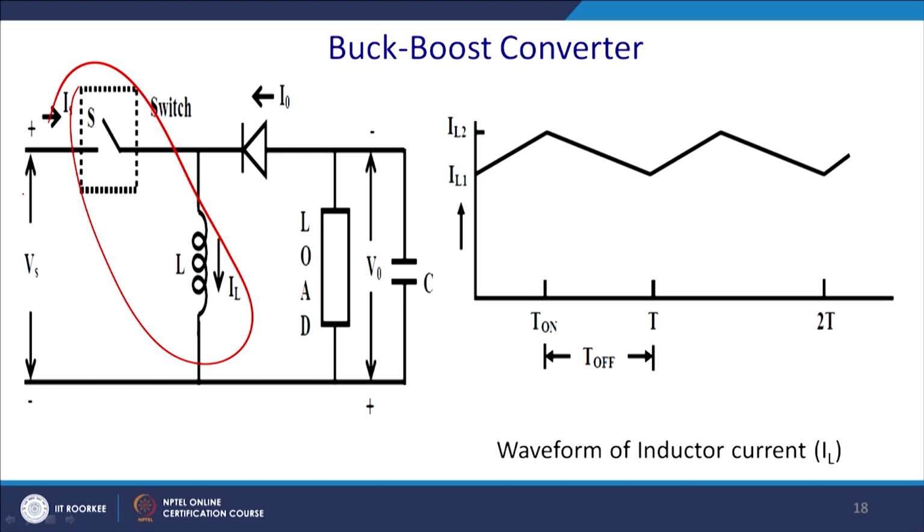So, the switch will be in series with the load, and the inductor will be placed in parallel to the load. When the switch is on, essentially this gives you the boost topology, because here there is an inductor and a switch, and here it is just interchanged.